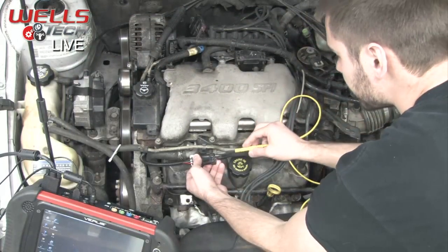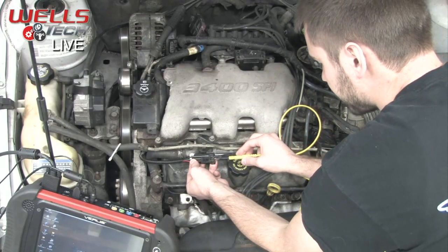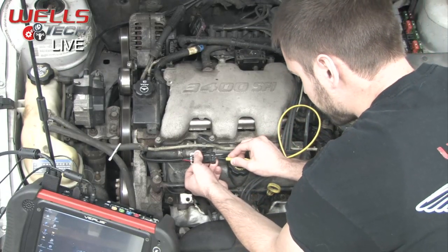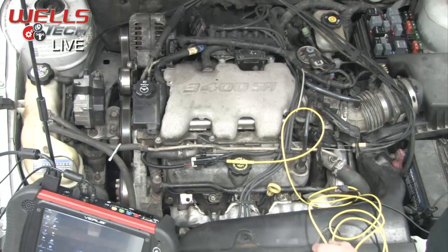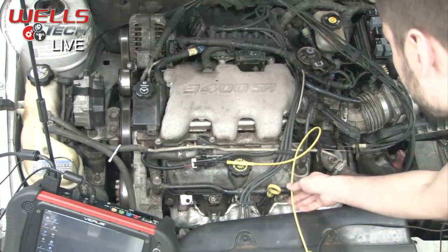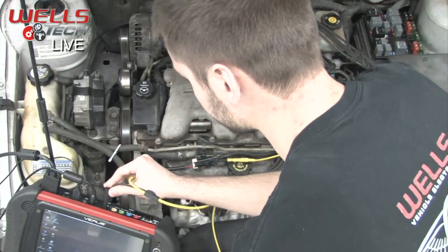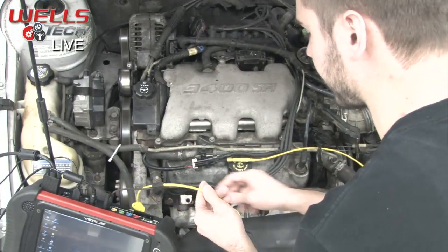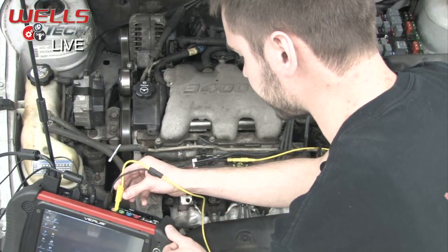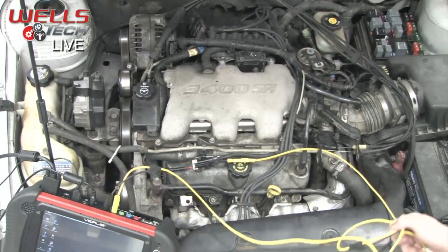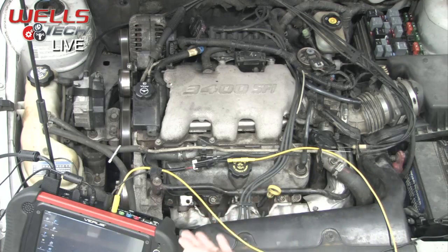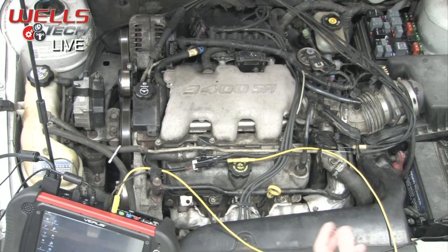So here's our cam sensor. We'll hook right into the back of that. And there we go. And then hook the other end of our leads up to this scope. Now remember, when you hook up the scope, you have to have ground. So I'll hook the black wire in there, which goes to our battery negative, and then the yellow lead into channel 1. I chose yellow for our lead. We have a bunch of different colors, but yellow is the channel 1 color. So when we get more leads on here, more channels working, it helps us stay organized that way. You can discern one from the other.